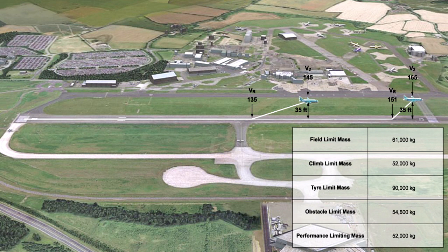This ensures that the climb performance significantly improves. As a result of the improved climb performance, the climb limit mass can increase, which would increase the performance limited takeoff mass and provide an improved regulated takeoff mass.